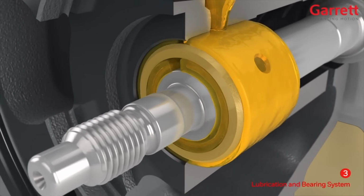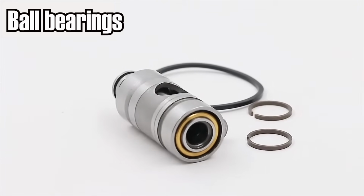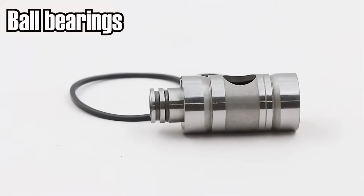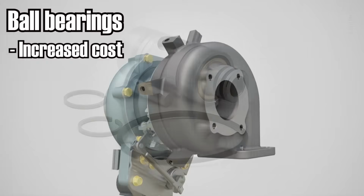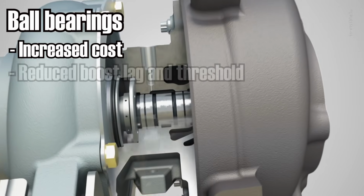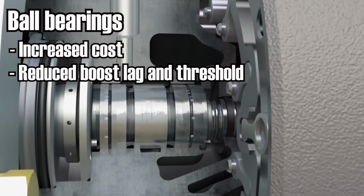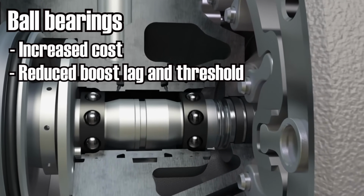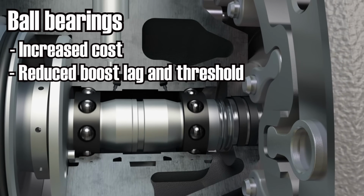Ball bearings, their only real drawbacks are that they offer a very slightly reduced lifespan and that they're more expensive, but they also offer a reduced rolling resistance, which means that they can reduce both boost lag and boost threshold. Typically, they reduce boost threshold by 100, 150, maybe even a bit more RPM, whereas their effect on boost lag can be even more noticeable.